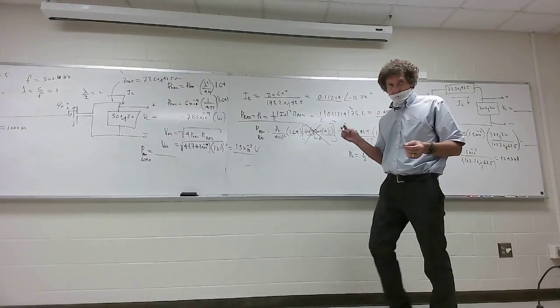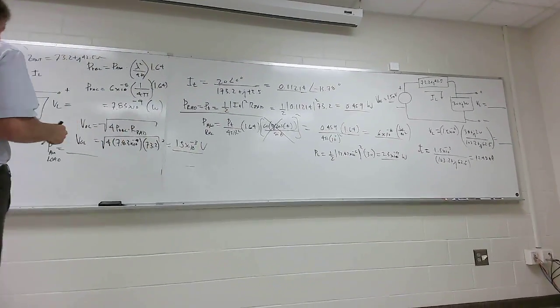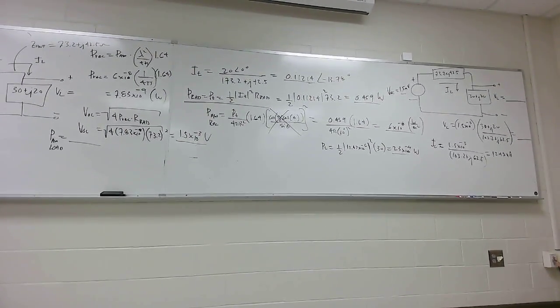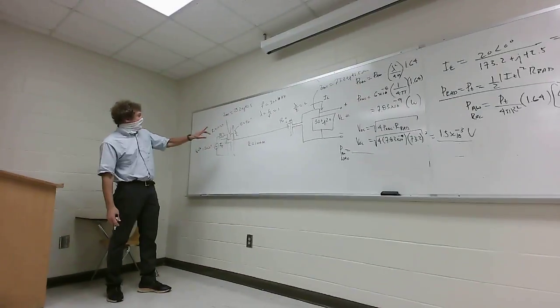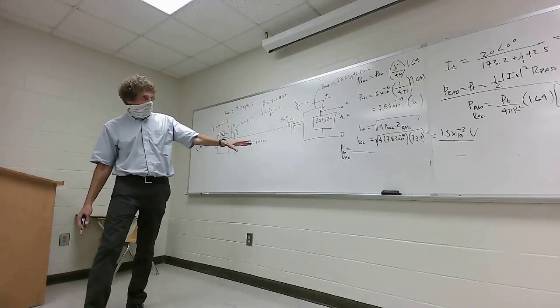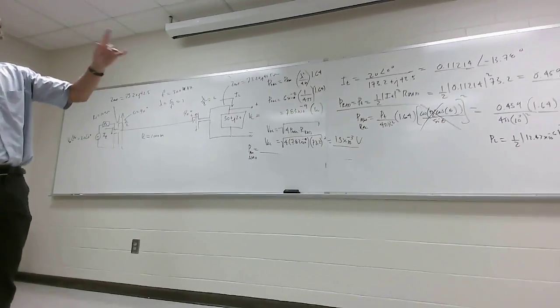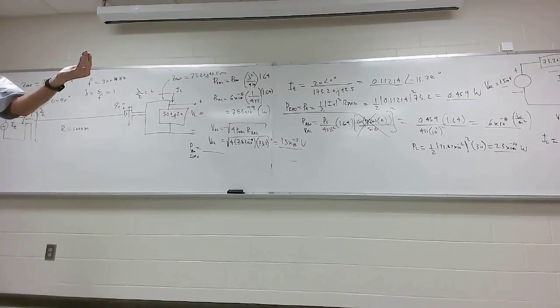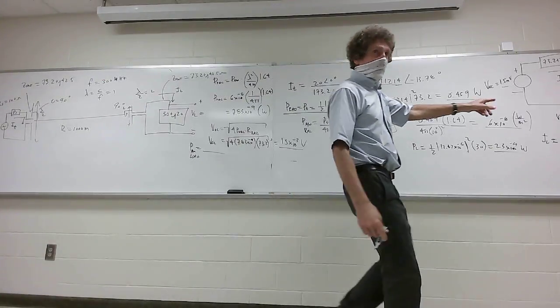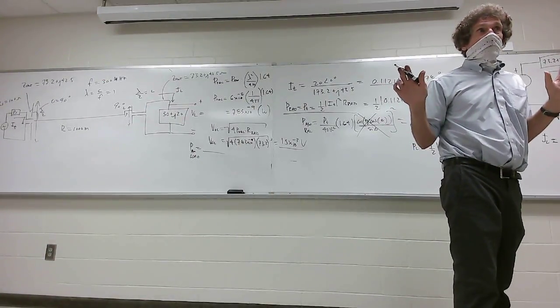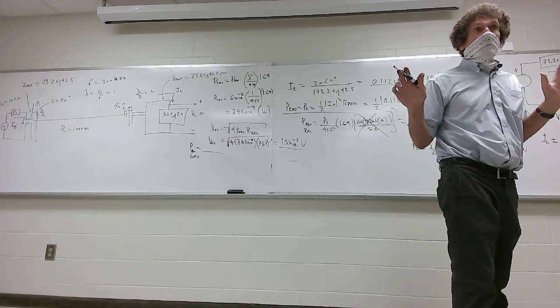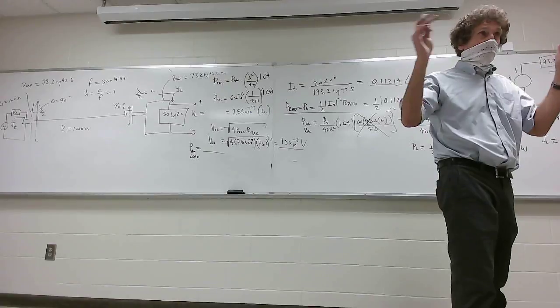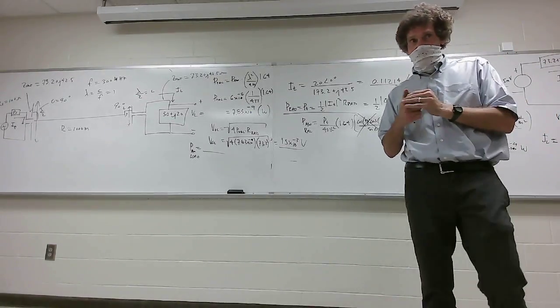All right, I want to make a point. We got a little over 2 nanowatts. And how much did we transmit? How much power is transmitted? Half a watt. From half a watt down to a couple of nanowatts at only 1,000 meters, right? That's nothing. Now, with high gain antennas, what you're going to see is the amount of power I can get out at 1,000 meters may be only a 1,000th of the actual transmit. In other words, it's a whole lot more. That's the purpose of high gain antennas. We'll do that next time, but I wanted to get through this example. I think it's important.